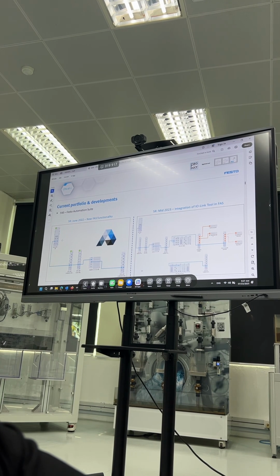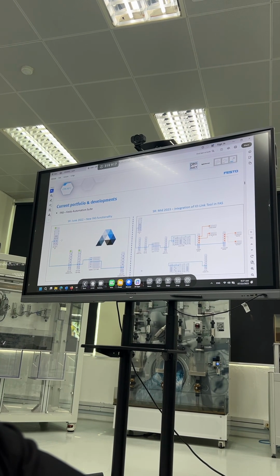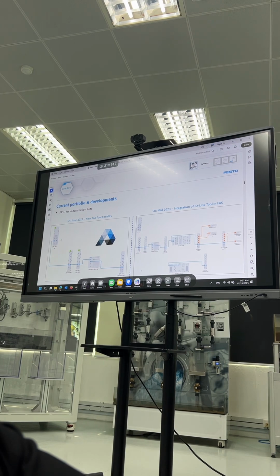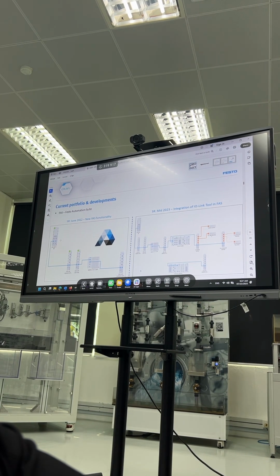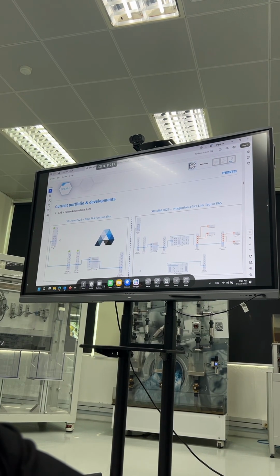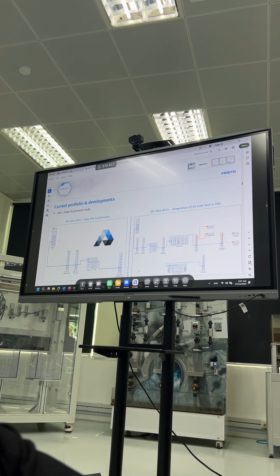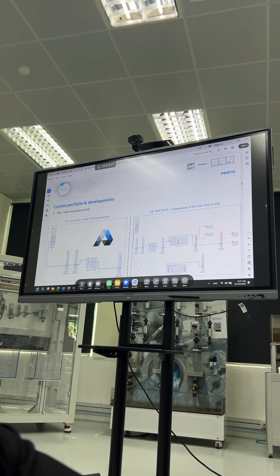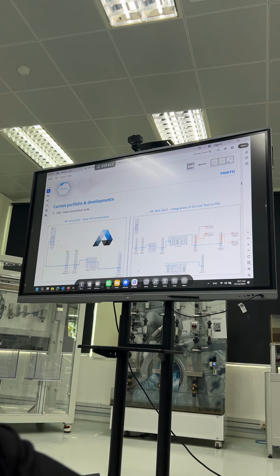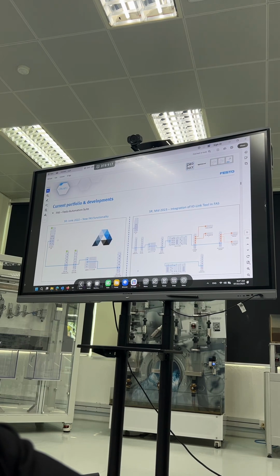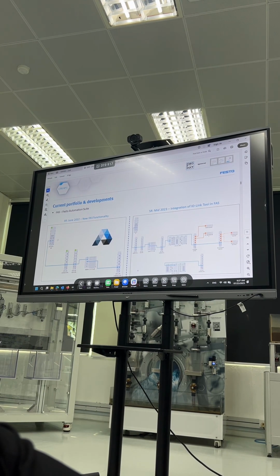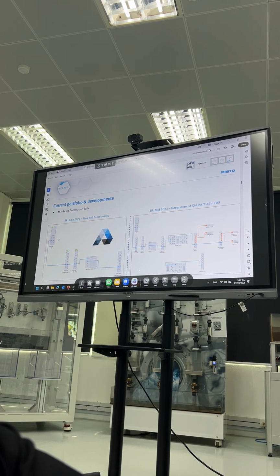And for EtherCAT, there are a few things you can do. If you are connecting to a PLC, you will need to enable what we call Ethernet over EtherCAT in order to connect to the web server. I'm not sure if this is available for every PLC, but for a Festo PLC, when you are configuring the EtherCAT slave, you can enable a function called Ethernet over EtherCAT.